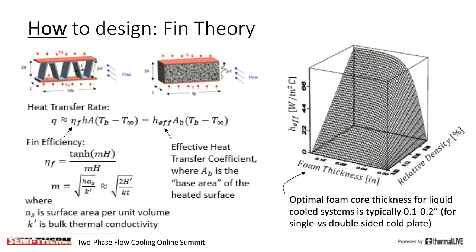Another thing to note is that in liquid and two-phase systems, the optimal thickness of the foam core is on the order of 0.1 inches, or about 3 millimeters, since beyond that point, the performance saturates due to fin efficiency effects.